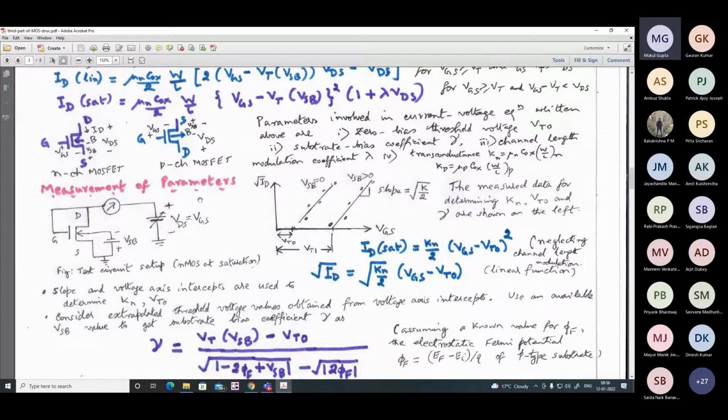And as far as the lowest value goes, it can be as low as the threshold voltage. Suppose the threshold voltage is, say, 1 volt. Then the least value that you can bring up and get measurable current will not be 1 volt. It will be somewhat higher, because if you have VGS exactly equal to VT, the channel has just started to appear.